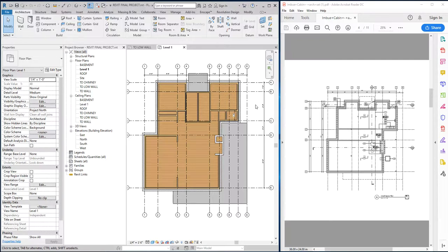The reason I like to add foundation walls from the main level is because of the way that foundation walls generate, okay? If you think of a house as, the main floor is a plane, regular walls generate, you define the base constraint and they grow upwards, right? That's how a wall grows. But foundation walls, they grow downward, essentially, right?